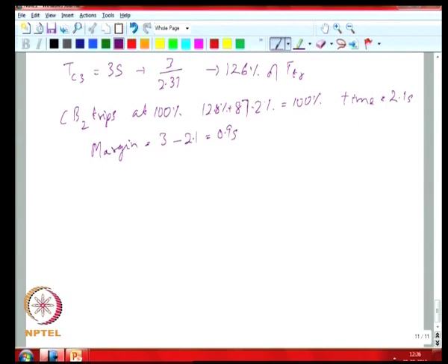If you have a fault in zone 2 or further downstream, in zone 3 etc., your current level can come down below 600 amps. So, there is a possibility that at some reduced current level your recloser might actually lock open before the downstream device acts.